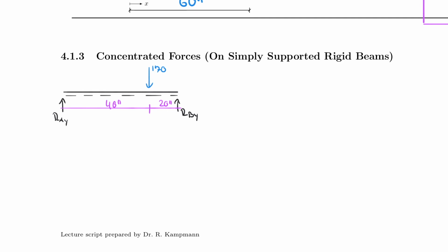And you may already have guessed it, or you may already have seen that in the table. There is a relationship between the geometry and the numbers that the scale gave us, but the question is why, right? So if you want to try something, it doesn't hurt to write down the sum of the forces in the y direction being equal to 0, and usually upwards positive, right?